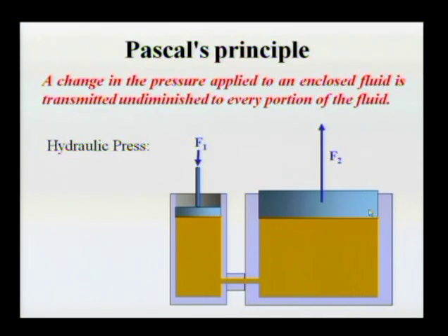That force will be equal to the pressure of the fluid at this surface multiplied by the area of that surface. The pressure over here is the same as the pressure over there. So I divide the magnitude of this force by the area of this piston. This gives me the pressure here and here. Now that force requires that I multiply the pressure by that area. So if I have an appropriate ratio of the areas, I can apply a much higher force. The hydraulic press will move a much heavier object than the force I can apply.